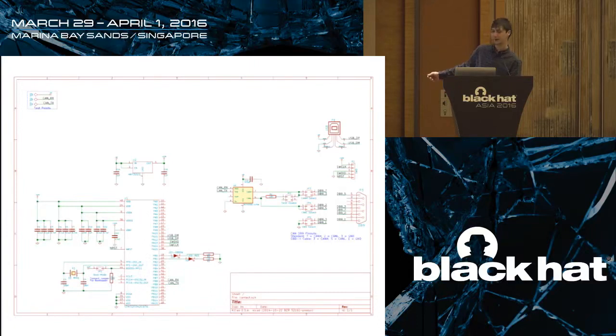There's a pinout for debugging. There's a jumper that you need to short out if you want to do a firmware update over USB. DB9 connector and USB. That's kind of all there is. Some test points, you're good to go. It's really nice when the whole schematic fits on one slide. And if you want to look at it in detail, of course, it's available online.